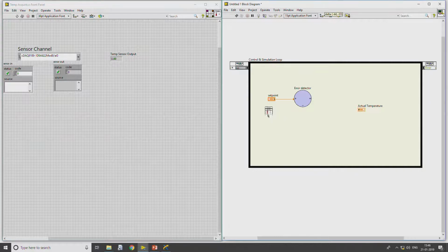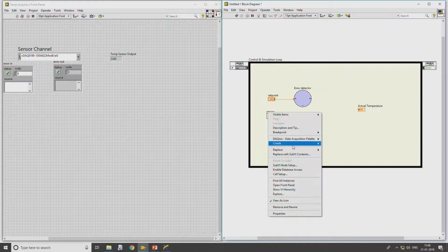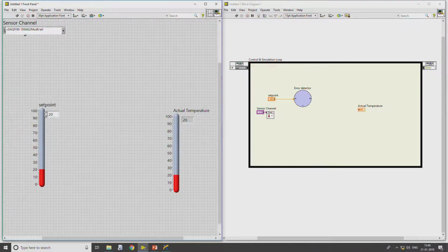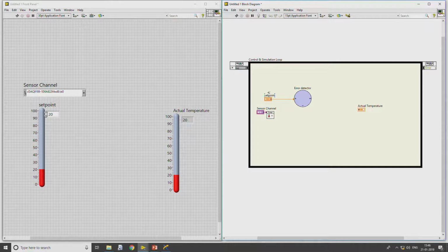Here we can see, whatever output we get, we have to provide the channel. So, create control, I am creating a control. Since the default is this particular channel, it will automatically be set. Now, what is the mapping factor that we consider for the set point? If you recall, the mapping factor we use is 1 volt per 10 degrees centigrade, meaning if I provide an input of 1 volt, the system will understand that it has to operate at a temperature of 10 degrees centigrade.